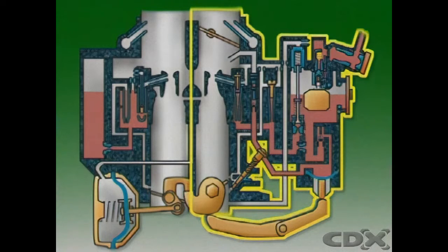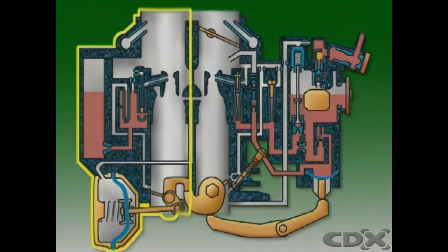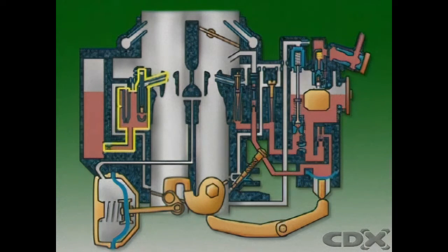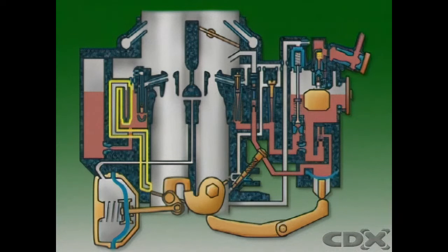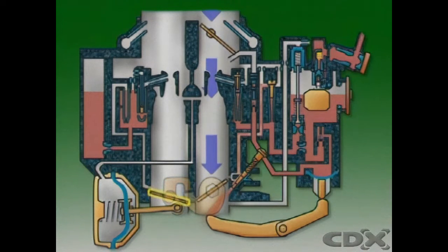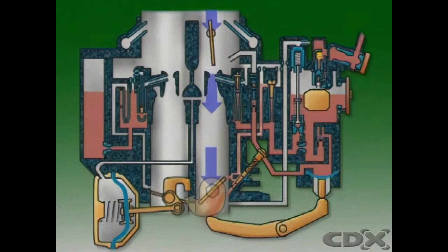This is called the primary side. The other barrel, the secondary side, supplies extra mixture, but only at high speed or full throttle. It normally has a main metering system and a non-adjustable idling system. The primary side has a choke for cold starting. When the engine is being started, the throttle on the secondary side is already closed, so a choke isn't needed.